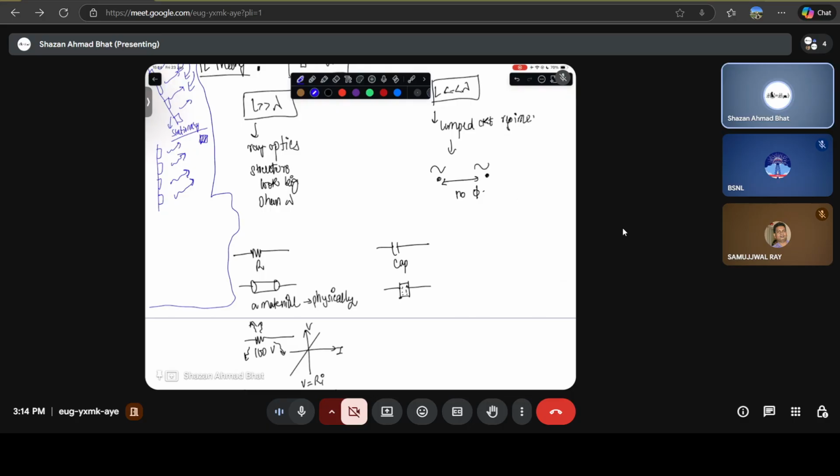So what you do is, because this is a transmission line, you feed in a certain voltage and it gets delayed a little bit. At one, it has a certain delay. At second, at third, at fourth, it has different delays. And those delays are basically phase delays in the waves. Let's say, for example, this has a delay of 0.1 pi, this has 0.2 pi, 0.3 pi, 0.4 pi. In radians, I'm talking about.